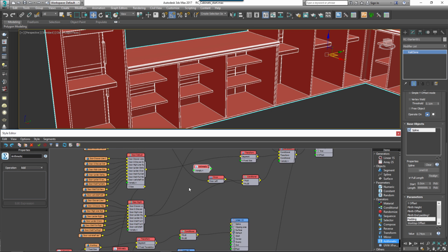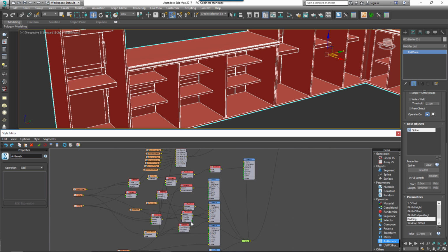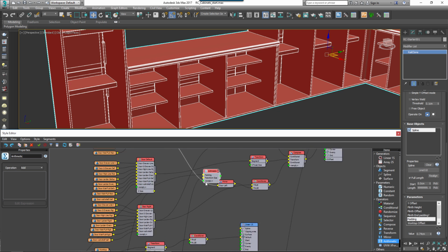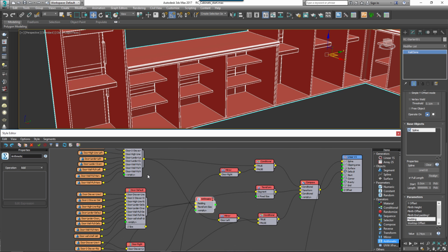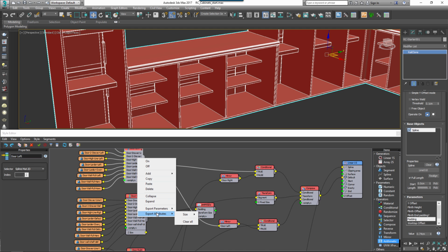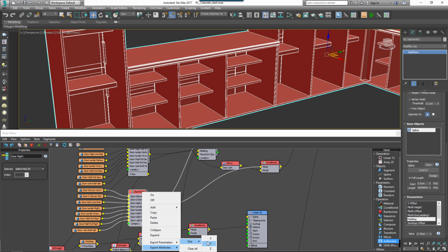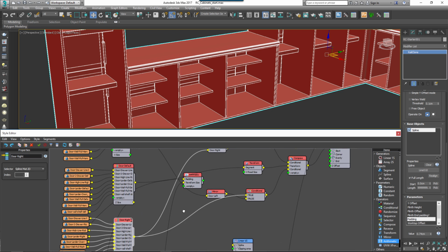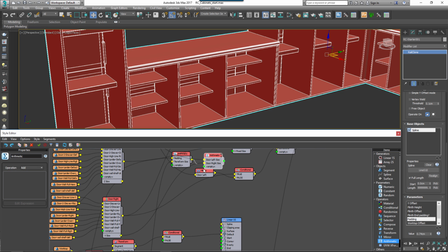To do this, create an arithmetic operator and attach the door padding numeric node and the X size of the frame carcass sides. Now you know why we exported it earlier. Then export the X size attribute for both the left and the right selector nodes. Then create another arithmetic node and attach both these X size attributes and the arithmetic operator we just created to the inputs.